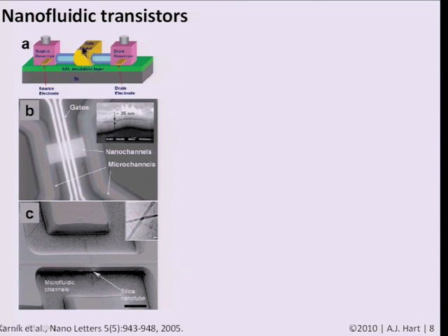And by applying a voltage between this top gate electrode and the fluidic environment, they can alter the surface charge of the tube. So it's like a little nanochannel with a width that is in proximity to the Debye layer thickness at the concentrations they're working at, and they can modulate the conductance or the flow of ions through the channel by changing the surface charge. Basically, if you have surface charge of one sign or another relative to the bias you're applying across the device, you can change how much pressure you might need to flow the ions across, because the charges on the surface and the ions that adsorb on the surface are exerting forces in that environment.